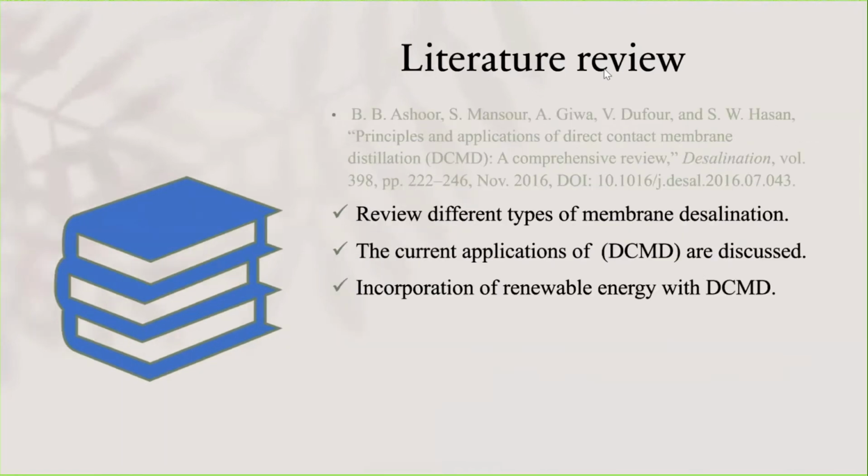By Ashur et al. It is titled Principal Application of Direct Contact Membrane Distillation (DCMD). It's a comprehensive review that gives most of the basics about direct contact membrane desalination and MD. MD is a thermally driven membrane separation process where only the water vapor molecules in a hot feed can move through the pores of the hydrophobic membrane.